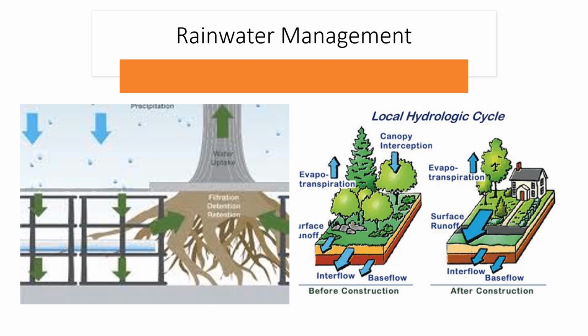You can get up to 3 credits for rainwater management. The purpose of the credit is to control runoff and improve water quality for restoring the natural hydrology of the site, managing both quantity and quality. Quantity control is used to slow the rate of runoff, maintain the natural flow, and promote infiltration. To do that, you need to control the rainwater. Quality control uses best management practices, or BMPs, to reduce the amount of pollutants that enter water and improve water quality.